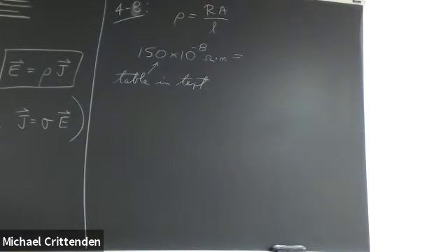As I said, the resistivity of nichrome is relatively high for a metal, which is what makes it good for these types of purposes. The heat generated in a resistor is equal to I squared times R. So more resistance means more heat generated for a given amount of current going through it.